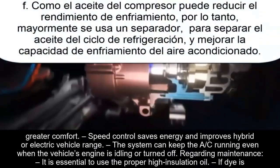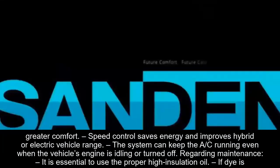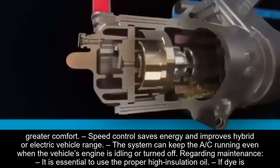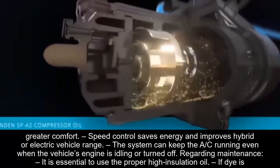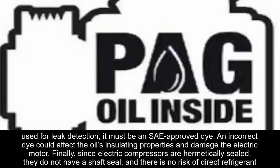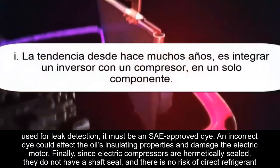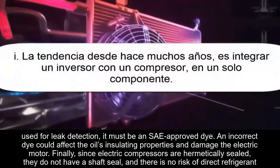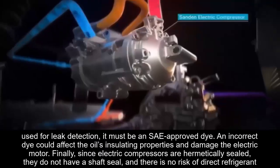Additionally, electric compressors are quieter, providing greater comfort. Speed control saves energy and improves hybrid or electric vehicle range. The system can keep the AC running even when the vehicle's engine is idling or turned off. Regarding maintenance, it is essential to use the proper high insulating oil. If dye is used for leak detection, it must be an SAE-approved dye. An incorrect dye could affect the oil's insulating properties and damage the electric motor.